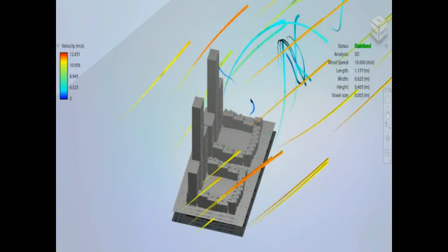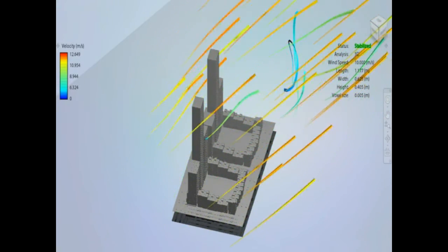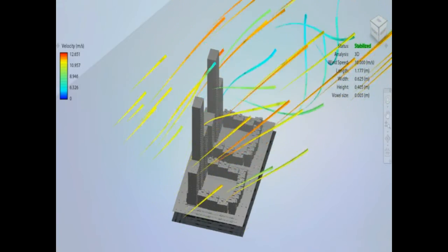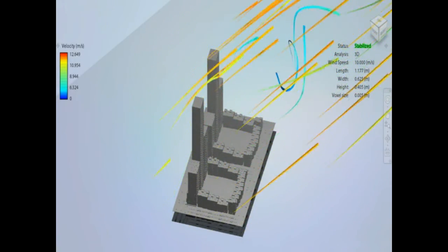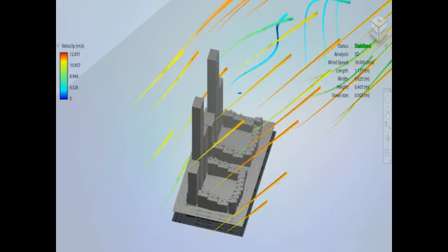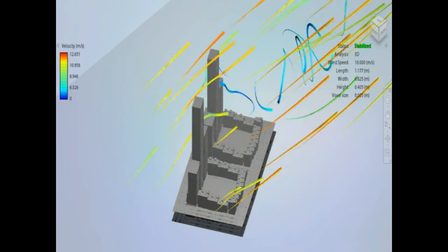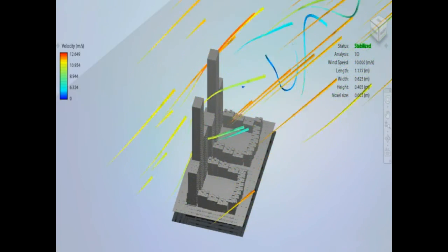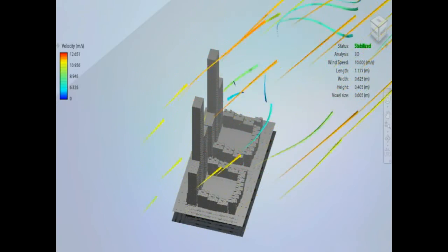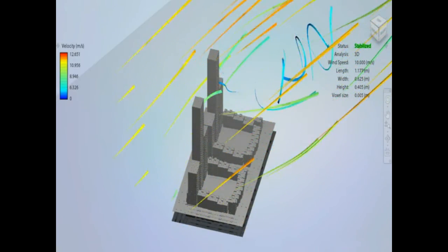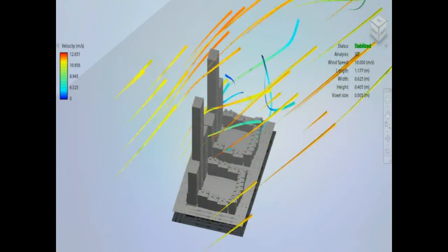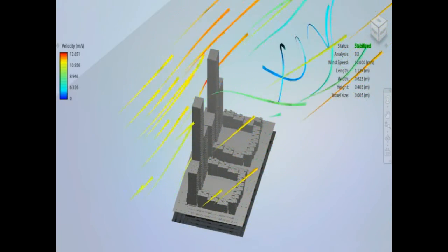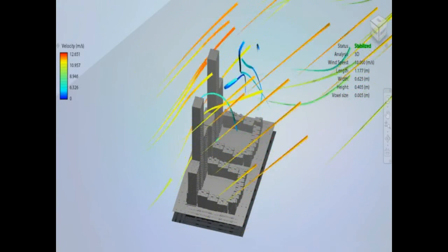The westerly winds hit against the narrower elevation of the tall buildings, rather than the wider northern elevation. Therefore, the wind pressure on the walls is lower. As a result of all of these design tweaks, uncomfortable wind tunnels and wind vortex do not form. Most of the wind speed at ground level is below the benchmark of 8.3 meters per second required for comfortable walking, as shown by the results of the simulation.